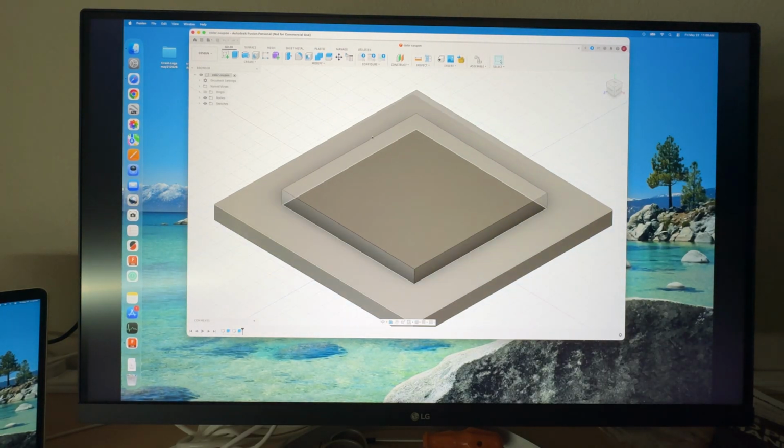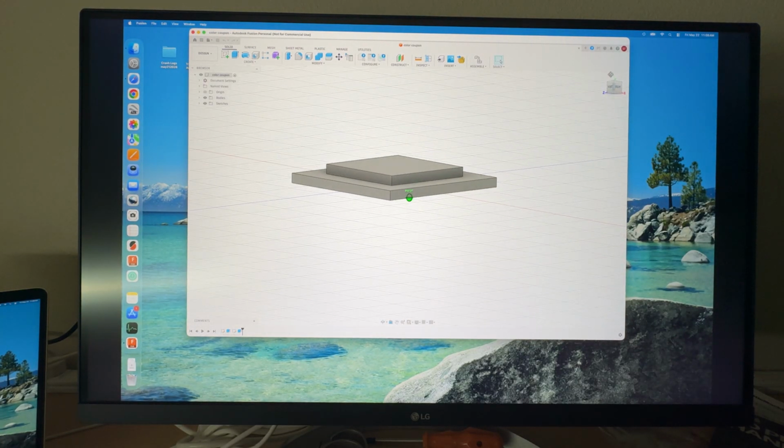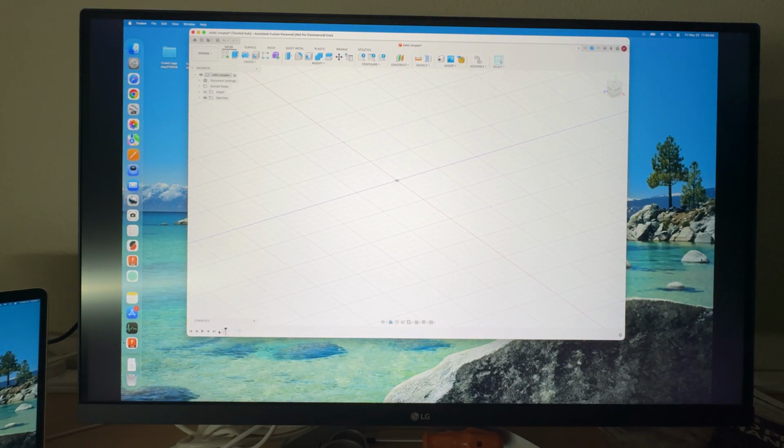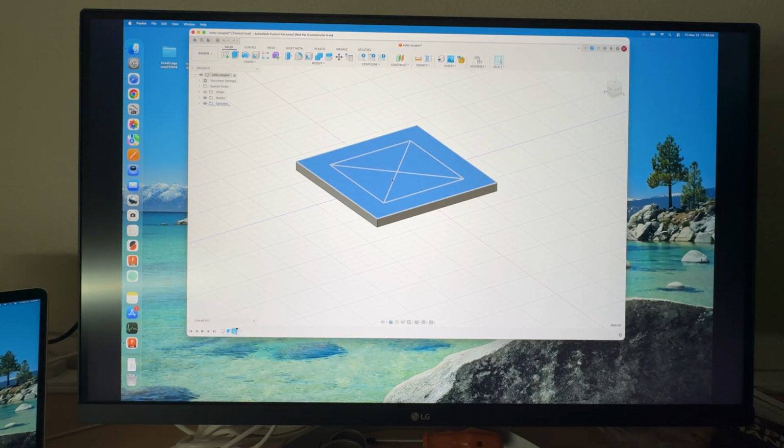Okay, well, here it is, and basically it's a fully functional little model of a very simple part. Down here, we can go down the timeline. We can take a look at the original sketch, and then we find that first extrusion right here. There's a sketch on the next layer up, which is right here, and then I proceeded to extrude that in the same direction. Oh, come on, Autodesk. Okay, so now I have this coupon.